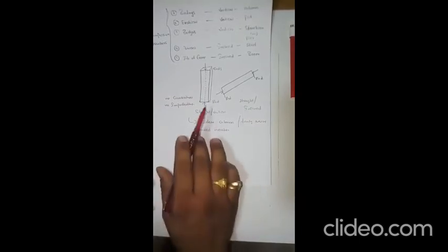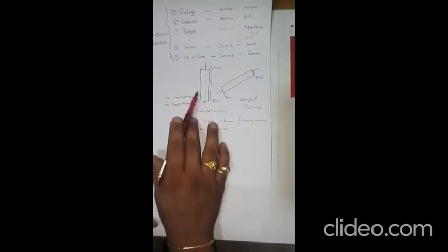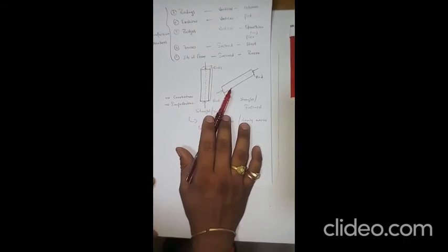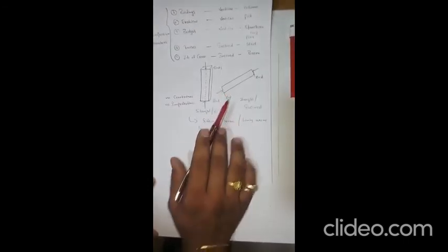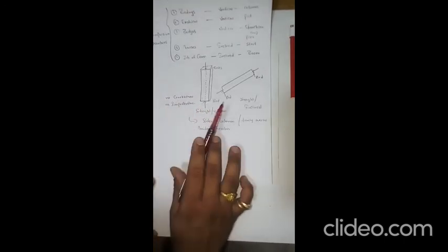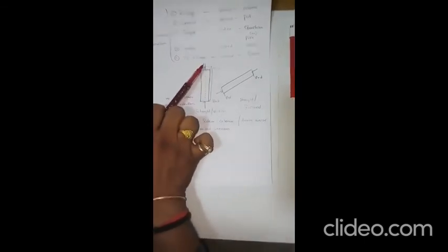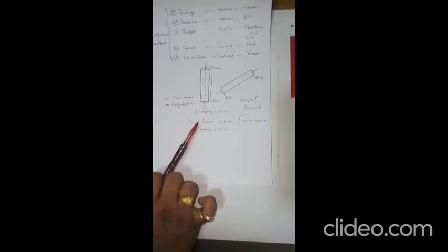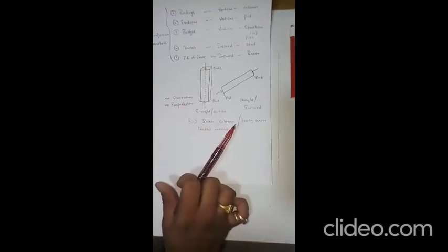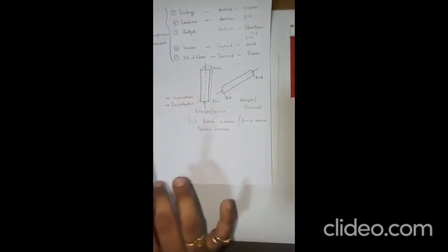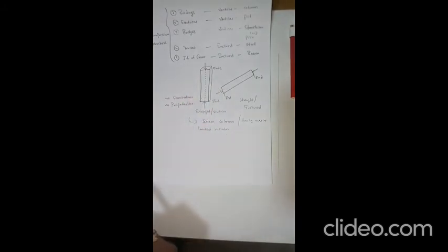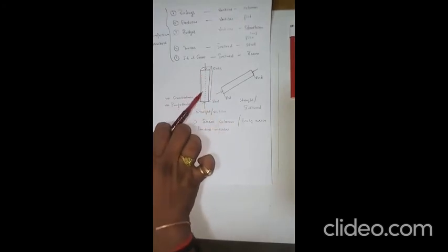However, the situations as stated above are impossible to achieve. Do you think this is possible? In practice, it is impossible to achieve; a perfectly axially loaded column member will never be encountered in practice. See, in practice, you can't expect that load should transfer axially from one end to the other end. So in practical, it is impossible. Why impossible? Because your column is not just an ideal column. Your column may connect with different beams. Your column may connect with a beam on the top. Your column connects again on the top. There will be a slab. So like that all loads should transfer to the column, and by that your column should transfer load exactly through its center of gravity.